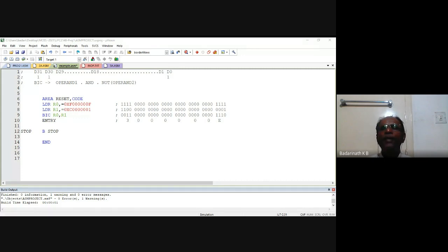So that is why in the case of the ARM microcontroller also, the overflow flag and the carry flag are not affected by these logical operations. The carry flag will change only if you introduce a shift operation in one of the operands. If you shift a number and then apply the logical operation, then whatever shifting you perform will be set into the carry flag appropriately. Because we know that whenever we perform any shift or rotate operation, the carry flag is affected. The last bit shifted out or rotated will go into the carry flag.